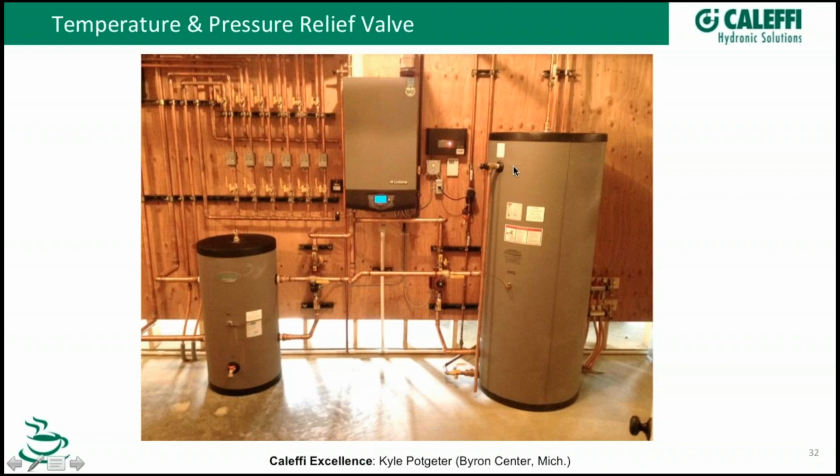And then the other thing, usually when they go off on high temperature, they won't reseat. There's a thermal element that comes off the back of this that goes in there and senses the temperature. That needs to be in the top portion of the tank. You can't have the thermal relief valve up here. It needs to be into the vessel, which becomes a challenge, as you'll see in the next slide, when you have a tankless water heater where you put the relief valve.